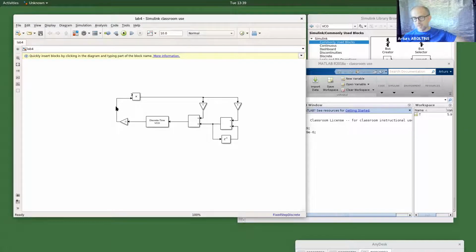So it ensures that the generated signal, this clock for the processor, is stable. Otherwise, you will have no way to generate a stable signal for 2 gigahertz, yes? And if you put in some configurable divider that you can manipulate from BIOS, for example, you can change the clock of your processor without actually replacing this crystal oscillator, because you can modify the dividers and you can overclock or underclock your computer and so on. So PLL has this very, very broad use, not only in communications.